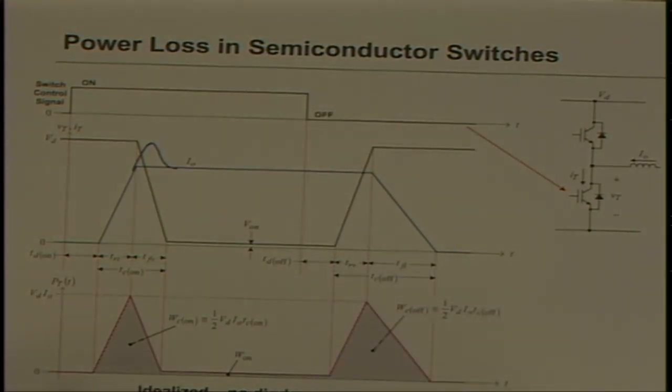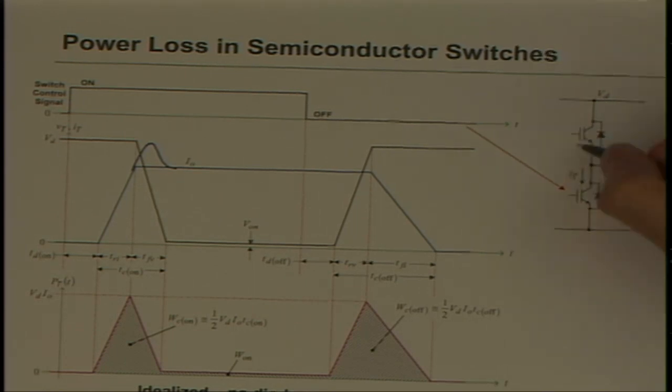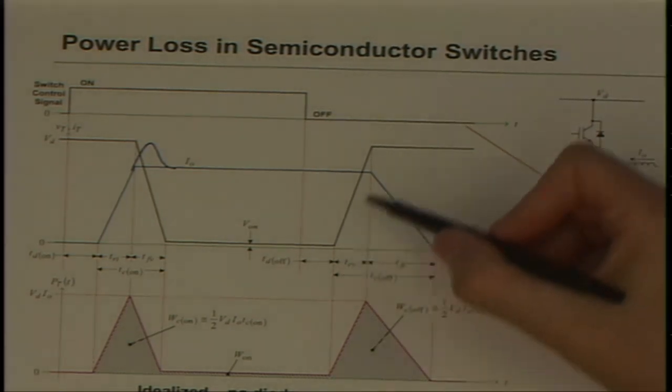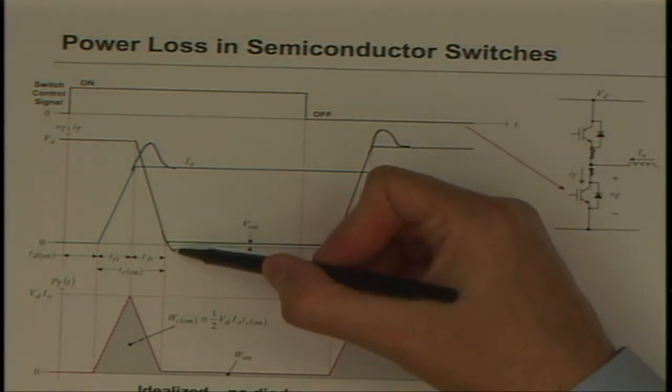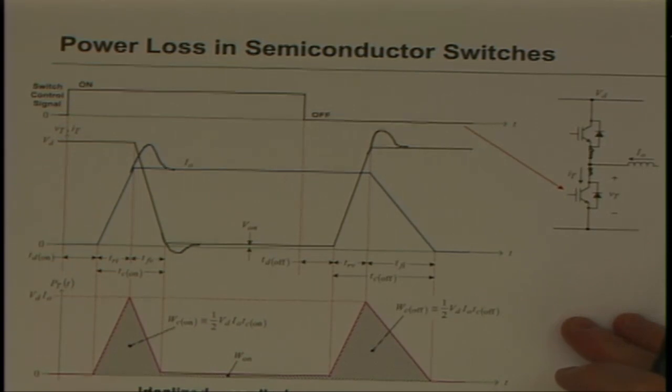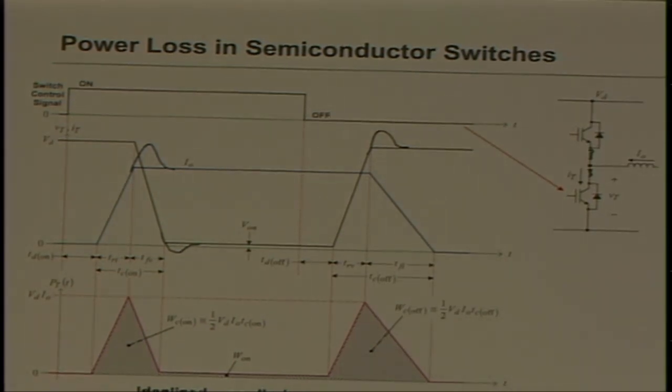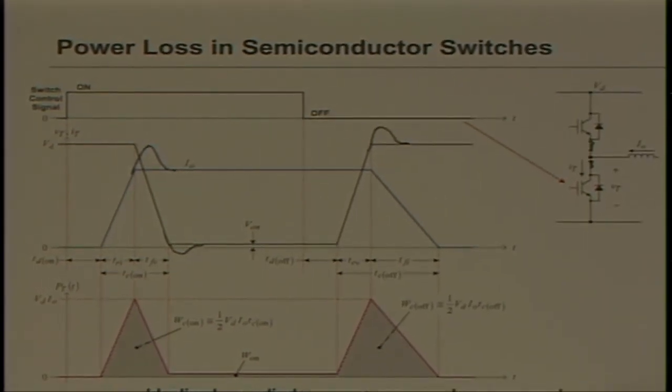And typically then as well, because there's distributed parasitic inductance here, you have a little bit of lead inductance here and here. The voltage at turnoff overshoots, and you get this kind of characteristic, right? So these are all the real world voltages and currents you see with IGBTs.